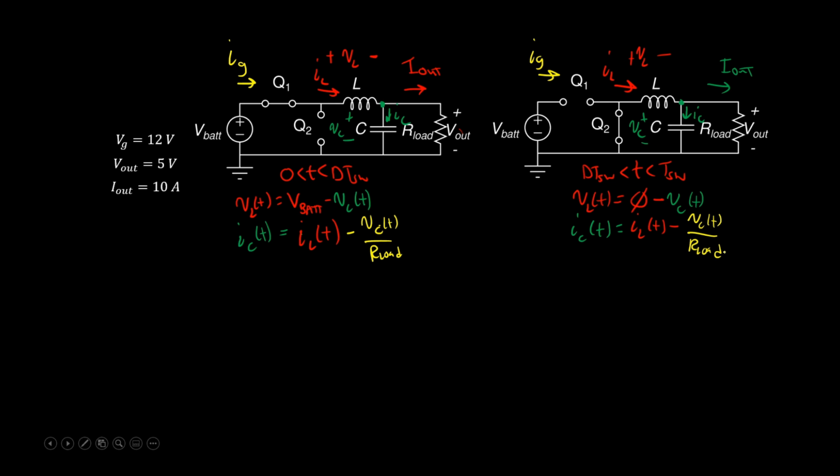All right, we're almost there. Or at least we're on step 1. Still on step 1. Now we can think about what signals we can apply small ripple approximation to. The rule of thumb we had before is that capacitor voltages, because we expect voltages to be constant, we can apply a small ripple approximation to them. We see VC of t here, here, and here. So we can apply small ripple approximation to basically all of these equations.